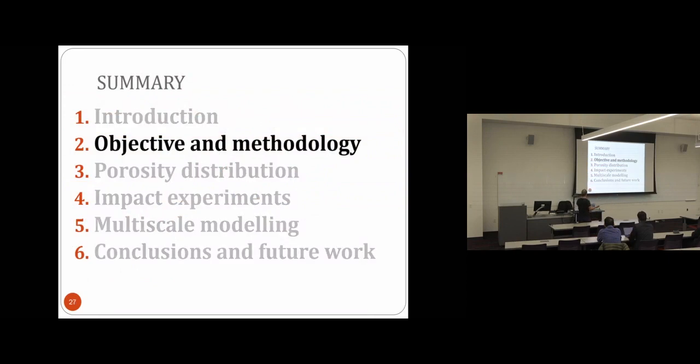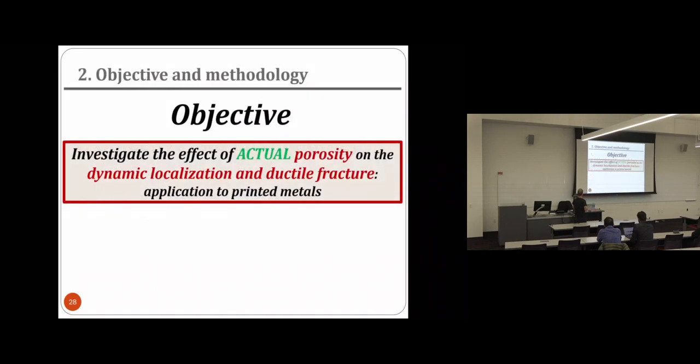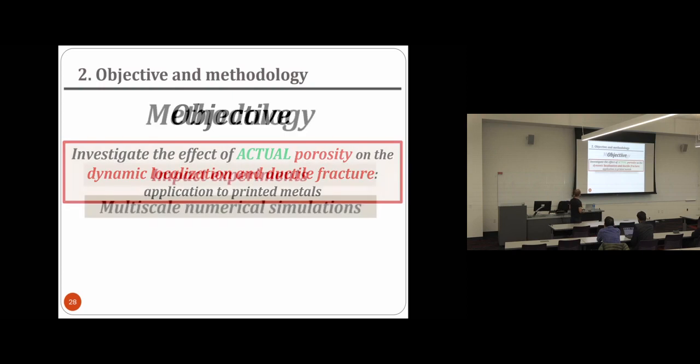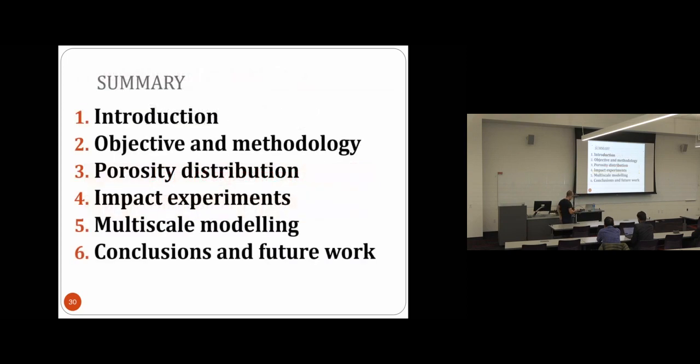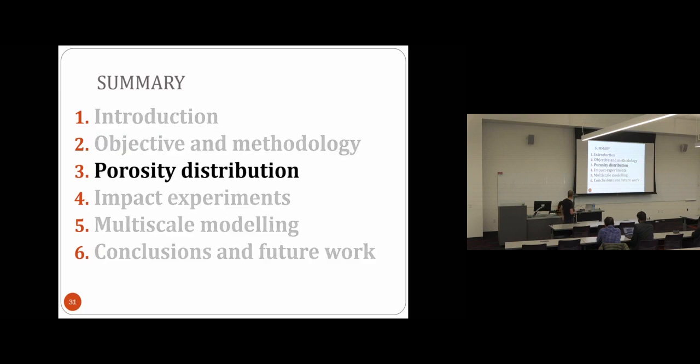Okay, so all this to say what? The objective, as I said before, I repeated it already several times, is to investigate the effect of actual porosity on the dynamic localization and ductile fracture with the application to printed metals. And we are performing impact experiments that I will show you now, and we are also running multiscale numerical simulations. We have done also a little bit of work on trying to develop analytical models, but this I will not show here. Still, we have some analytical models also for analyzing the problems that I have shown you before.